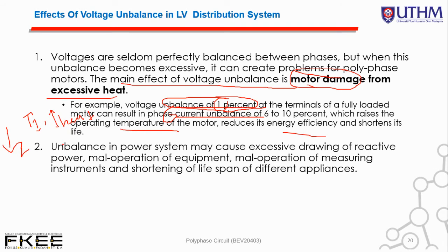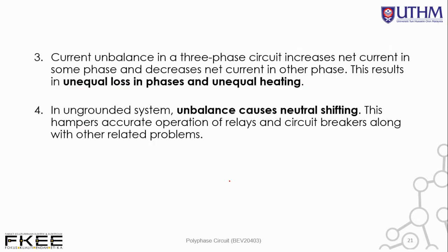Unbalance in a power system may cause excessive drawing of reactive power. This is again what we have gone through earlier. So it draws much excessive reactive power. It can cause malfunction of equipment, maloperation of measuring instruments, and shortening of the lifespan of different appliances.